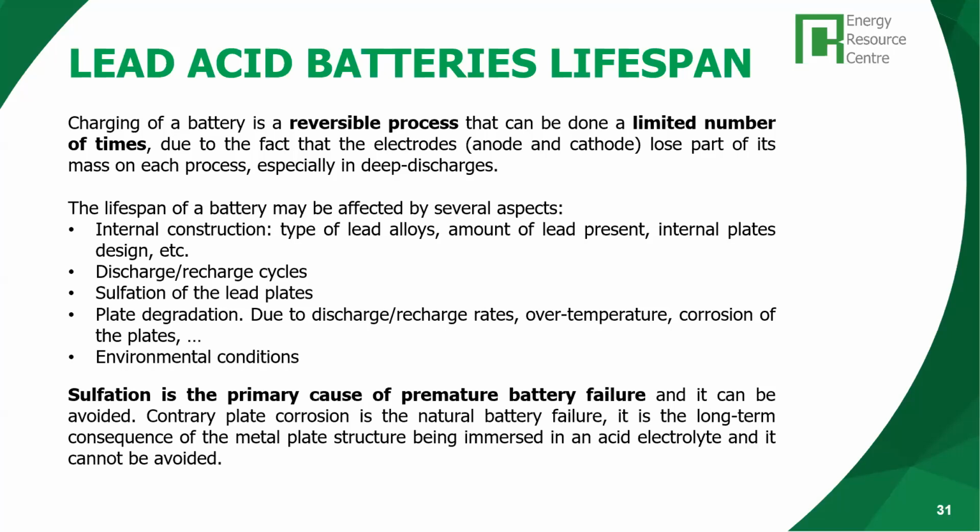Remember, when the battery is charged, there's a lot of acid in the electrolyte, and when it is discharged, there's little acid because the sulfate ions are stuck onto the plates. So that's a problem with lead acid batteries if they are discharged too deep, for instance, or if they are not recharged after a long time of being discharged.